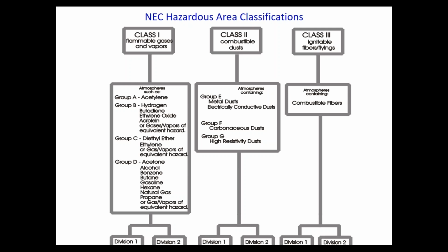forward. So you go into a customer and you say, what are you trying to look for? And the customer says, I need to monitor hydrogen. Well, immediately, as a rep and as a manufacturer, I can tell you exactly what products we sell that can be used to monitor hydrogen. It would be the catalytic bead, and the SafeCal is a group A, B, C, D enclosure. It's designed to see hydrogen.